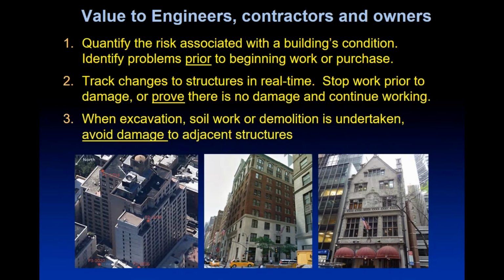And that signal, because of a potential failure of a single panel, had come through to positions up here and over here, quite some distance away from where the problem was. Now we are looking at vibrations in the structure, and we're drawing conclusions about what's going on. So the vibrations do transmit through the structure. And you can see from this example, quite some distance, we were measuring the effects of that delamination.